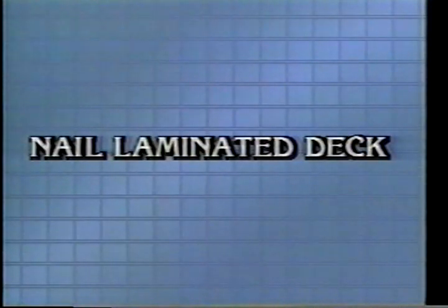We have a problem with many timber decks. The joints are the problem, so you do need a very solid timber deck to avoid cracking and propagation of cracks from joints through the asphalt wearing surface. If we talk about the types of bridges that we're putting in now, the old nail laminated decks used to have quite a bit of delamination, and so you had a joint between each lamination, and many of those would cause alligator cracking in the asphalt, and the wearing surface would break up, and you might not get more than 5 years of life from it.